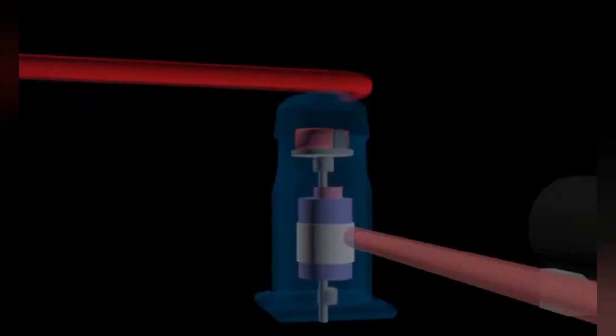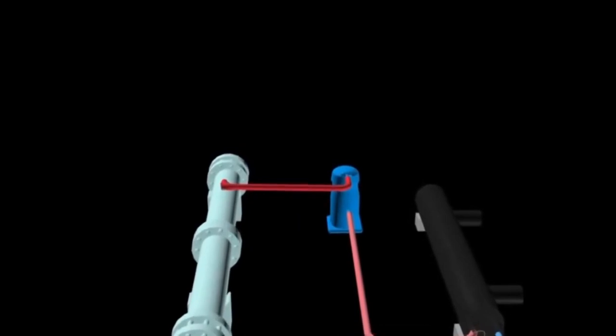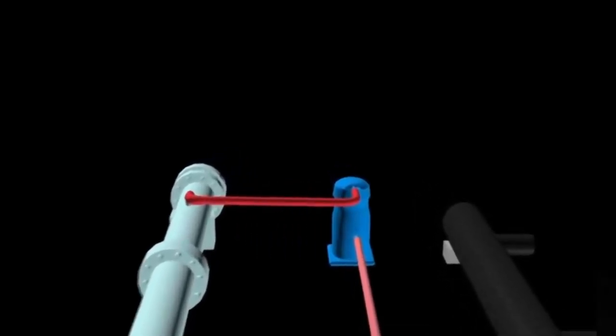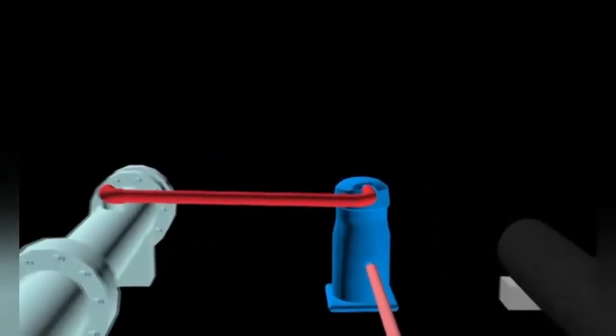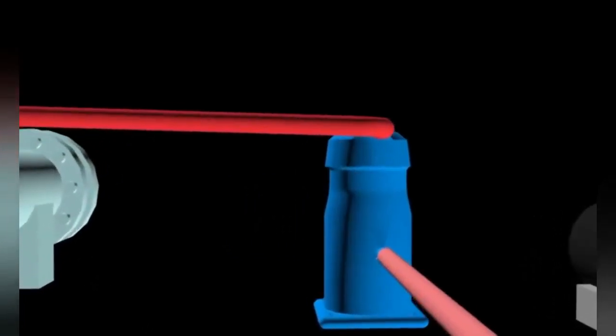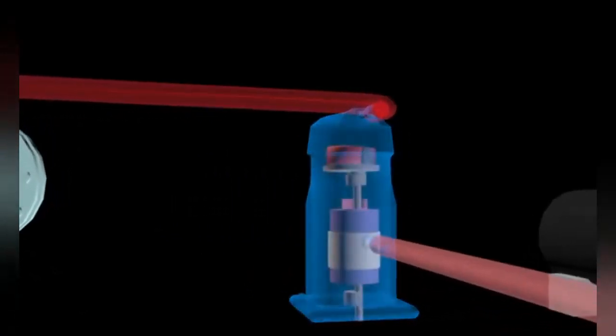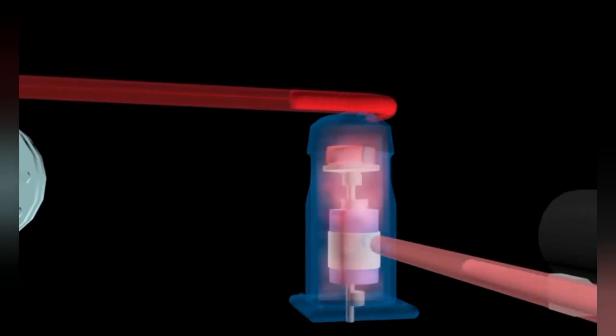Compressor. The compressor works to increase the pressure of the refrigerant. In addition, it also serves to increase the temperature of the refrigerant higher than the temperature of the condenser water so that the heat transfer can occur in the condenser. The refrigerant enters the compressor as a low pressure gas and leaves as a high pressure gas.